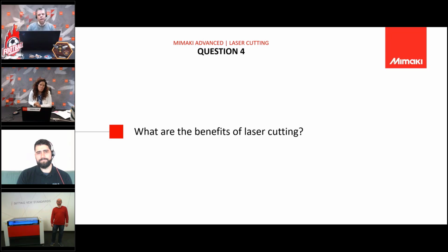The accuracy, and also when you're cutting through, for example, acrylic, the space that is left in cutting. I compare it a little bit with CNC routers, it's less. If you're cutting a star, it will be a star eventually, and with CNC cutters you have a space around it that has also been cut. So especially for making jigs, it's difficult, and for laser cutting it's super accurate, and I think the opening is only 0.2 millimeter or even less. It's really fast. That's also for paper cutting and textile cutting. It's some seconds and you're done.